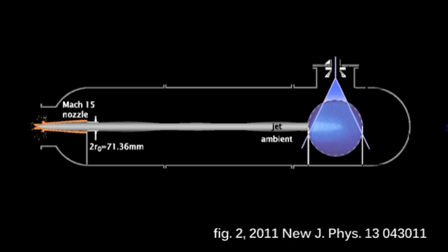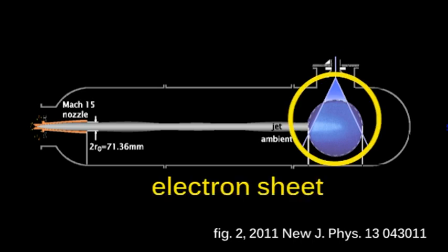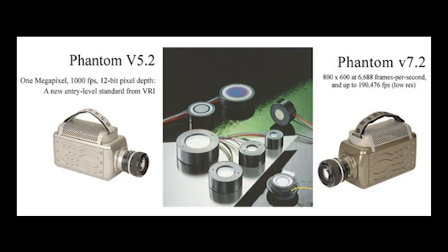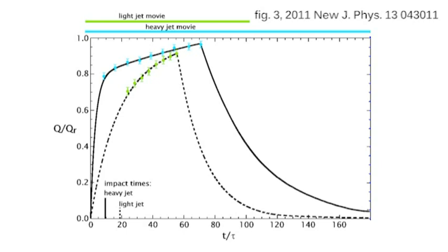An electron gun creates an electron sheet that intercepts the jet and generates a plane fluorescent section of the flow, which is then acquired by a fast camera equipped with an image intensifier. The numerical simulation is a complete reproduction of the laboratory experiment, which includes all the flow transient phases: acceleration, near steady state, and deceleration. This allowed a comparison of the results obtained from the two methodologies.